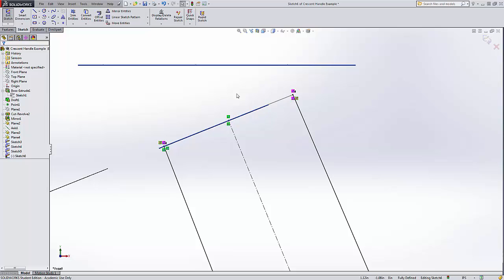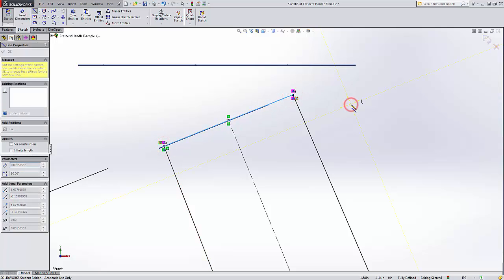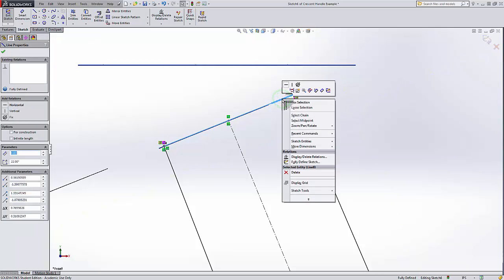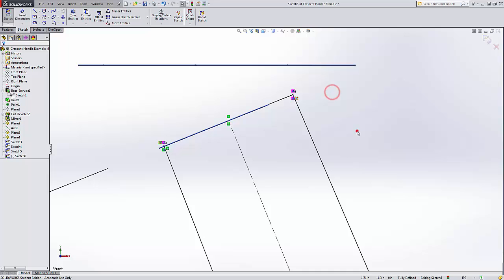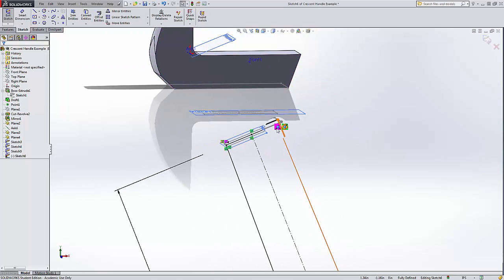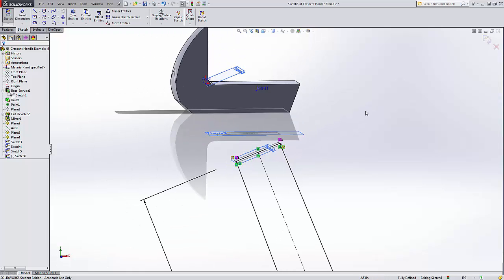Now I did not make a sketch line from here to here yet, so you may have wanted to do that first. But there we go. Make sure I didn't do it already. Oh, I do have a line from sketch 5. The sketch 5 itself, line 8. Okay, so this is the actual line that we just made. These two are from sketch 5 and that's sketch 5. So I'm all set. As one would expect, I've got these two lines from sketch 5, this one here and that one there, and then the one I just made. So we should have 3 lines underneath that.